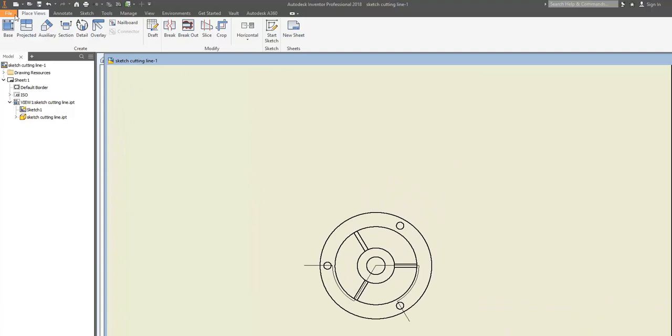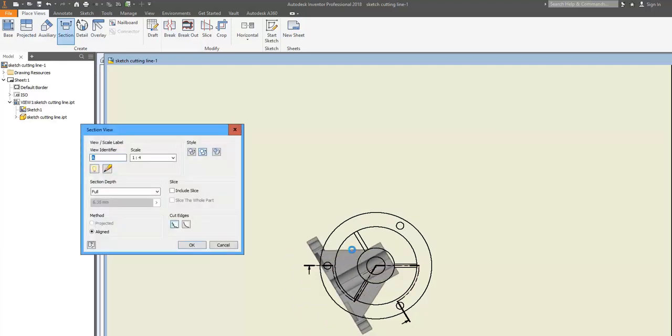There is a trick here. After clicking on the sectional view creation process, for the other sectional views, first indicate the view on which the cutting plane exists, and then draw the cutting plane line. But here, for aligned sections, after starting the sectioning process, the order is opposite. First, define the cutting plane line, where it is. Indicate the cutting plane line. Okay, and then the program will automatically understand that an aligned sectional view is needed.